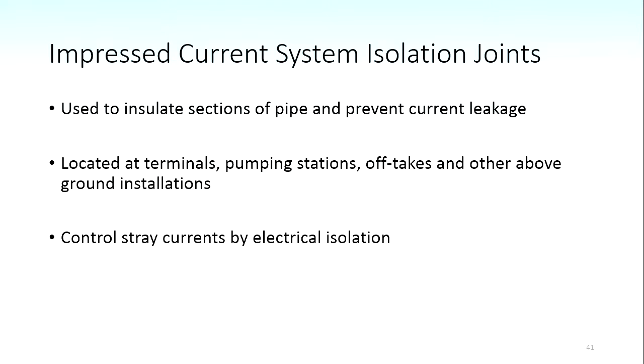And stray currents are an issue because they create scatter in your potential monitoring data. And so sometimes you actually have to put a data logger on and record the average potential over a period of time to get a better feel for what's happening on your pipeline.